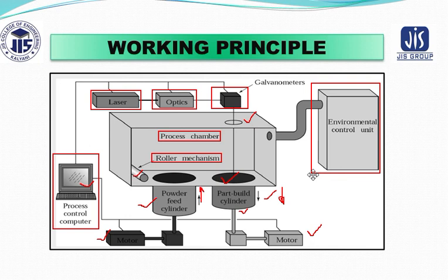So, as we are talking about deposition of material, that is also layer by layer. You can see that another layer of powder is deposited through this cycle, and you can see it has been performed repeatedly until you get the entire 3-dimensional part that is required, or that is your ultimate product. Now, the loose particles are then shaken off and the part is recovered.